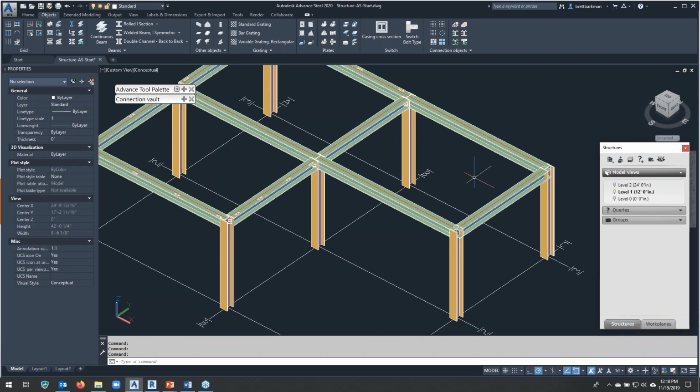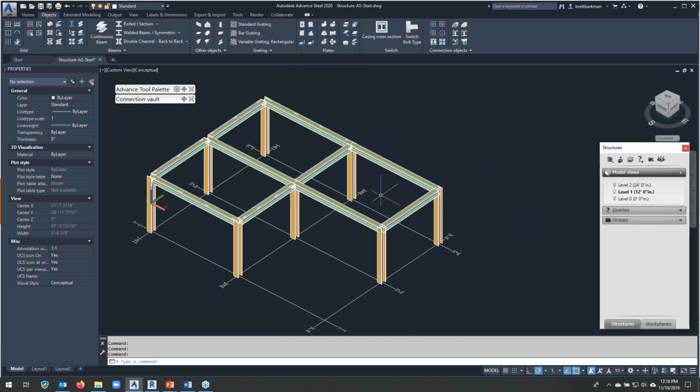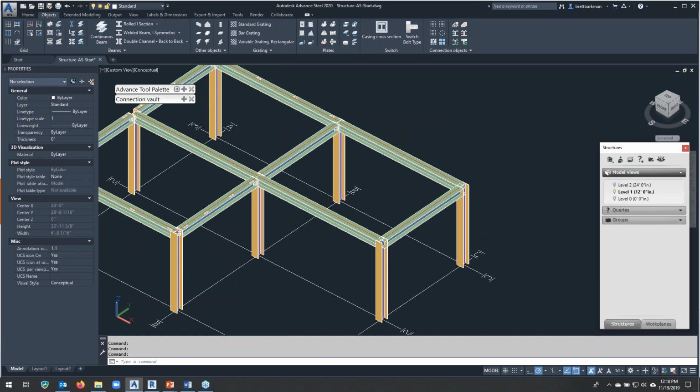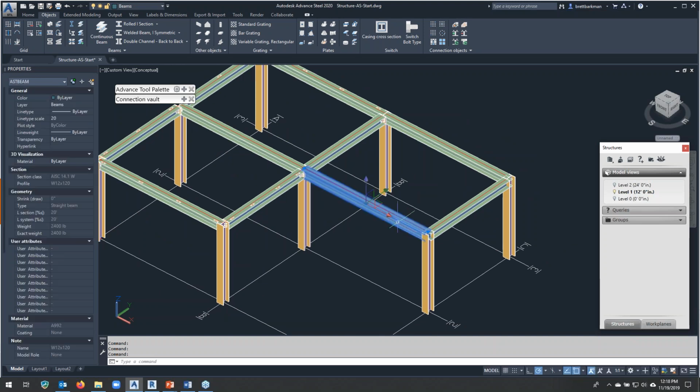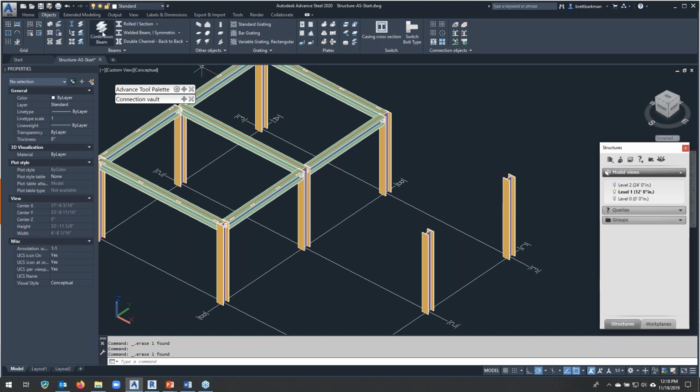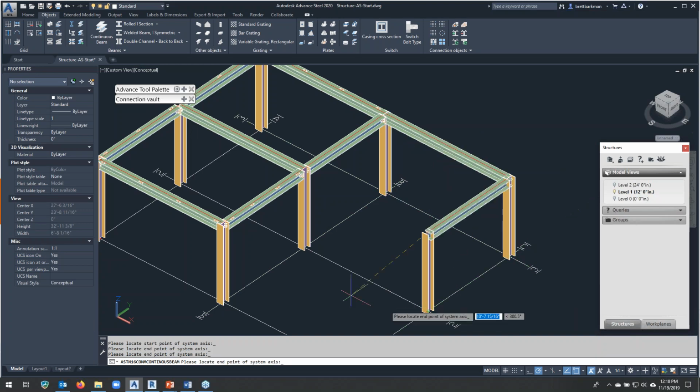So if you're a 2D user, you prefer looking at things from a plan view, then you can do that. Or if you like to work in 3D, then it's okay to orbit back and watch things develop in 3D fashion. To illustrate that, I'll delete these 3 beams and just replace them real quick. Just so you can see that even though I'm snapping down on the floor, the beams are being placed in the correct location regardless.